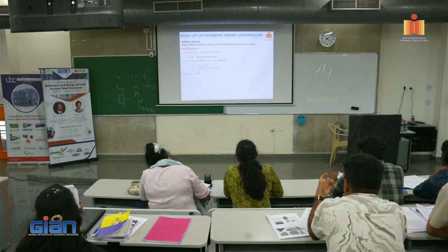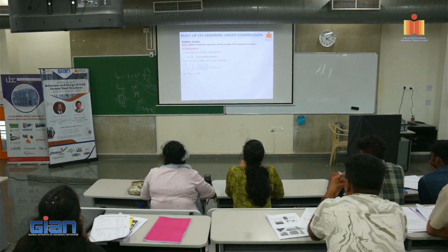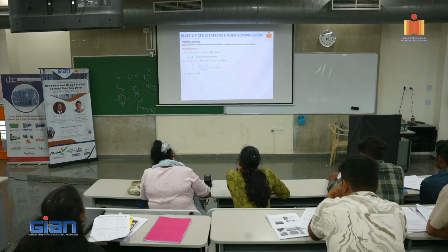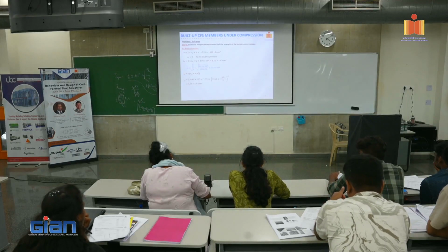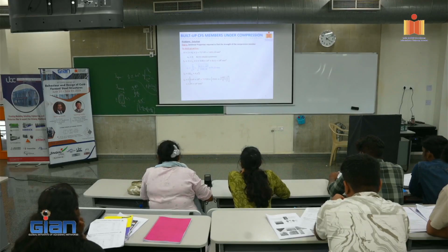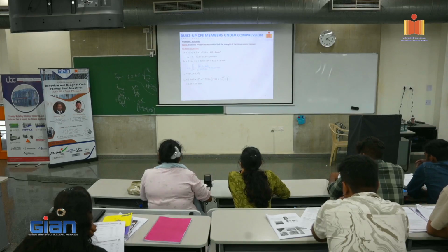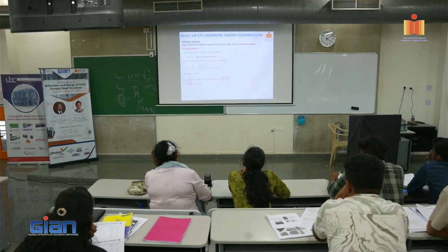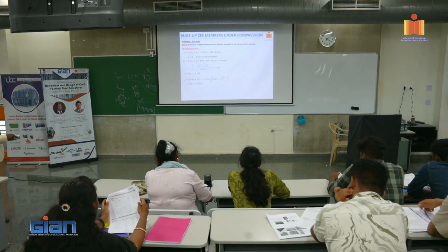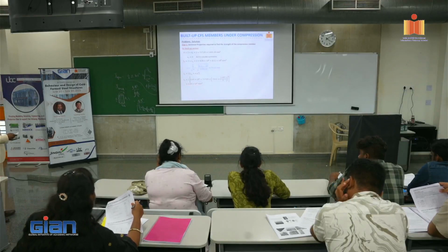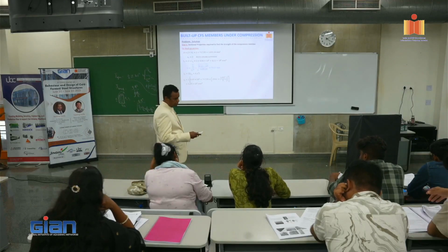Now Iy equal to the parallel axis theorem, right? A h square will come, right? So 2 times this, so 2 into Iy bar individual plus Ai individual plus xi square. When you do the numbers, it is 2 into this 0.49 into 10 power 6, which is Iy, plus A individual cross section 717.59 plus this distance. This is the xc bar distance plus the thickness divided by 2, which is xi the whole square. When you get this, you get 1.59 into 10 power 6. That is the Iy for the built up cross sections.